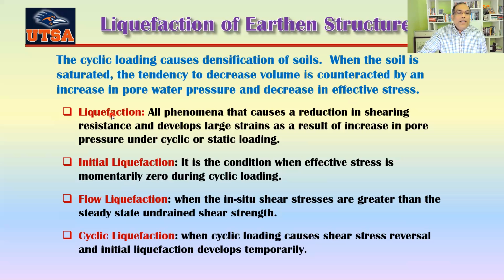So let's say here that of the four terms, we have to remember that liquefaction is all phenomena that cause a reduction of the shearing resistance and develop large strains as a result of an increase in pore water pressure under cyclic or static loading. Okay, that's basically liquefaction. What is initial liquefaction? It is the condition when effective stress is momentarily zero during the cycle.